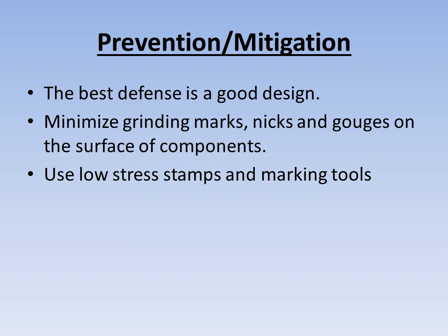The best defense is a good design. Select a metal with a design fatigue life sufficient for its intended cyclic service. Minimize grinding marks, nicks and gouges on the surface of components. Use low stress stamps and marking tools. These are some of the prevention and mitigation methods for mechanical fatigue. One of the main causes for mechanical fatigue is mentioned as grinding marks. So please note that point.